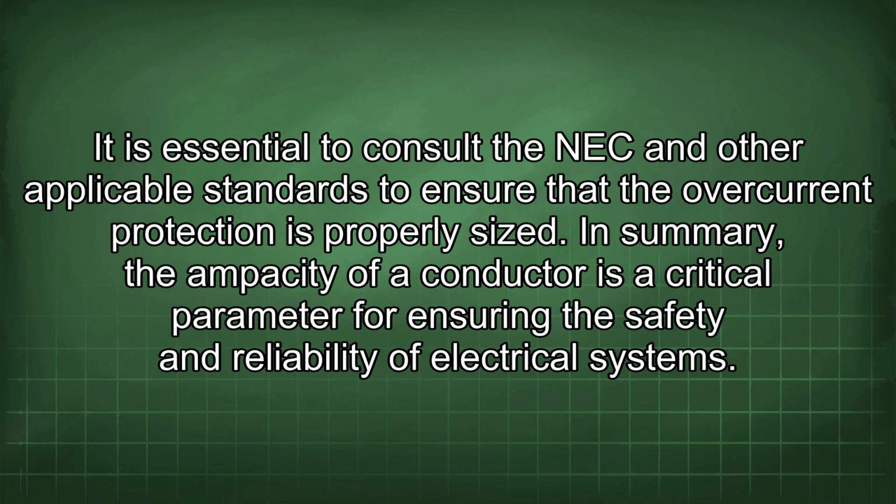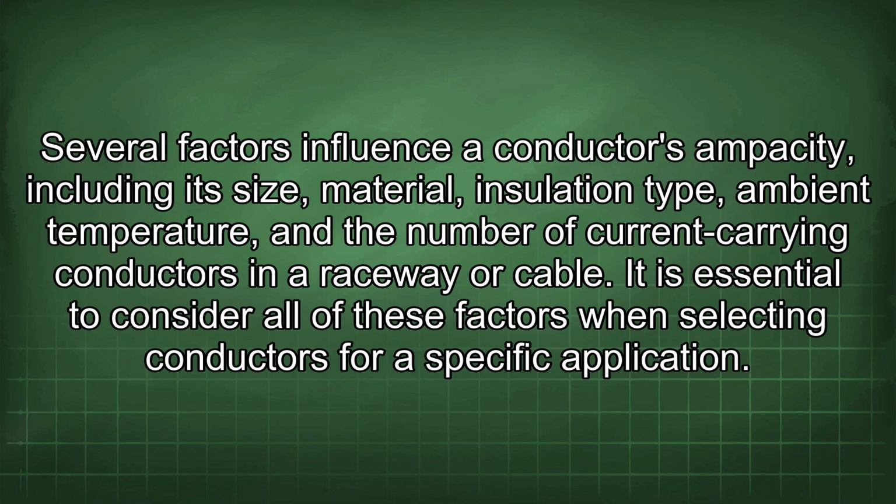In summary, the ampacity of a conductor is a critical parameter for ensuring the safety and reliability of electrical systems. Several factors influence a conductor's ampacity, including its size, material, insulation type, ambient temperature, and the number of current-carrying conductors in a raceway or cable. It is essential to consider all of these factors when selecting conductors for a specific application.